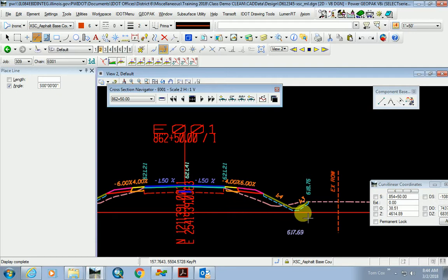I know I can't go with standard ditches because I know from a drainage standpoint, remember on this job, we're trying to get from that intersection down to that swale. So I'm going to need to look at the elevation at that intersection, the elevation down at the swale, and then somehow I need to have either a straight line profile or a profile with maybe a few VPIs in it. I guess we could jump into that real quick. I'm not going to reprocess, but maybe I could show you quickly how I would go about designing a special ditch profile.